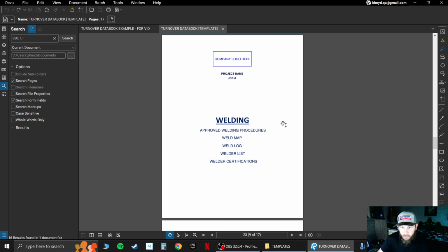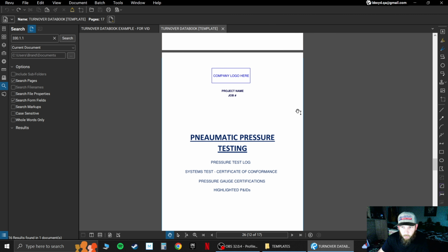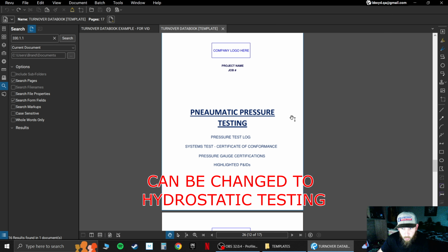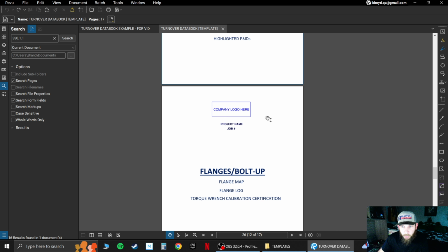Your piping ITP, heat map, your welding shows all your procedures, your map, your log, a list of your welders and those welder certifications. Your NDE section, you've got your RTs, your PTs. If you need to add MT, UT, anything else, you can add that in there. And then it also has a section for your technician certifications. Your pneumatic pressure testing section, which shows your test log, your COC if you need it, your pressure gauge certifications, and your highlighted PNIDs. I like to walk the systems down and highlight everything that's being tested, and I like to add those into my final data package.